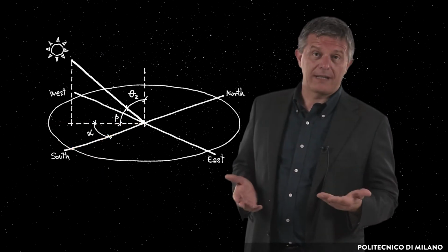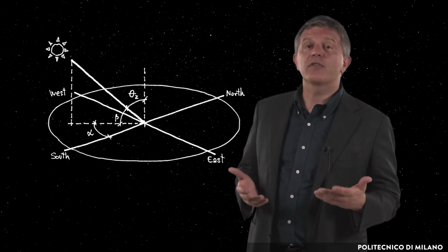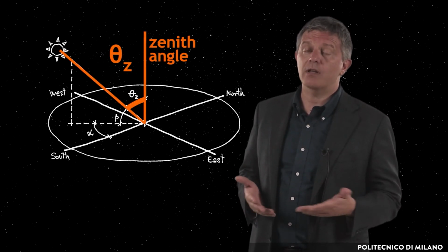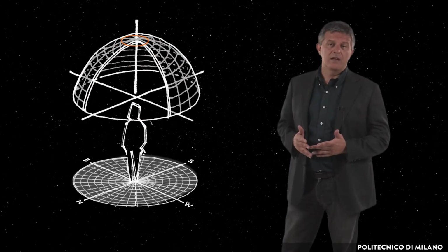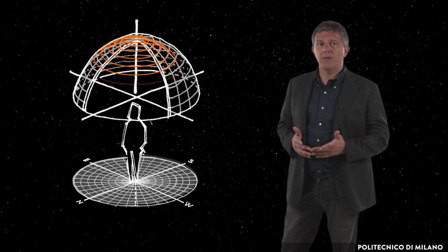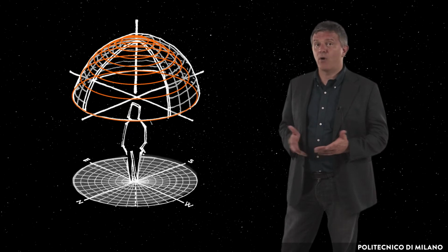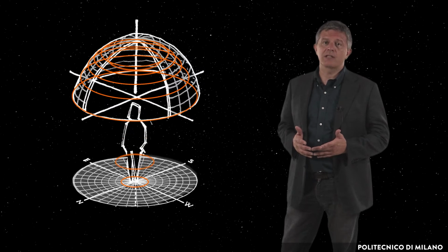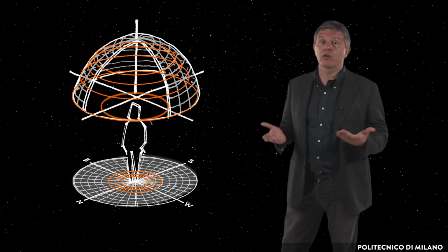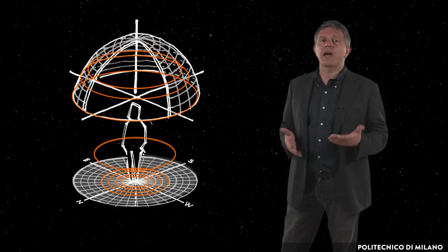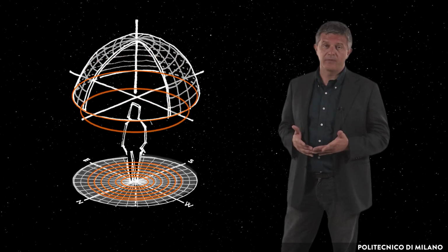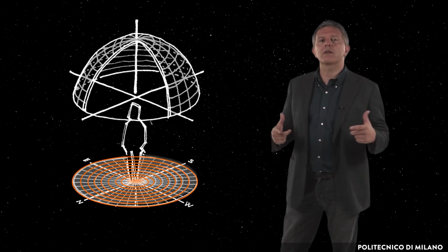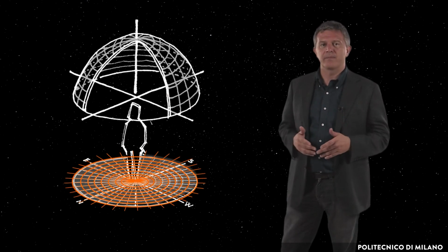It has to be noticed that in some of the literature, instead of the angle beta, the zenith angle zeta z is used, which is the complementary of beta. Solar paths related to a particular latitude can be read easily on the so-called polar diagram. In polar diagrams, solar paths are represented through a stereographic projection onto a horizontal plane, on which the four cardinal axes are represented. The base of each polar diagram is represented by a series of concentric circles and radial lines.